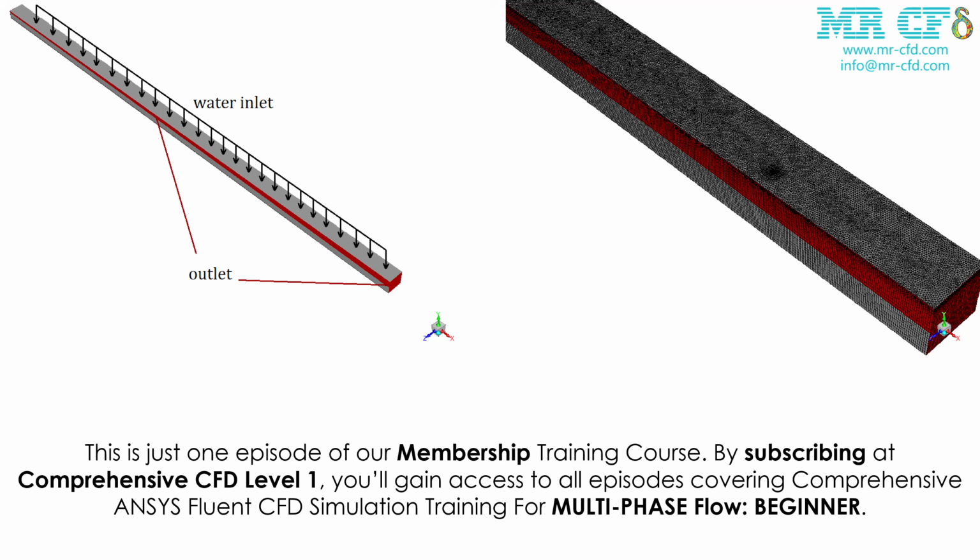The geometry of this project is designed in ANSYS Design Modeler and meshed inside ANSYS Meshing. The mesh type used for this geometry is unstructured.